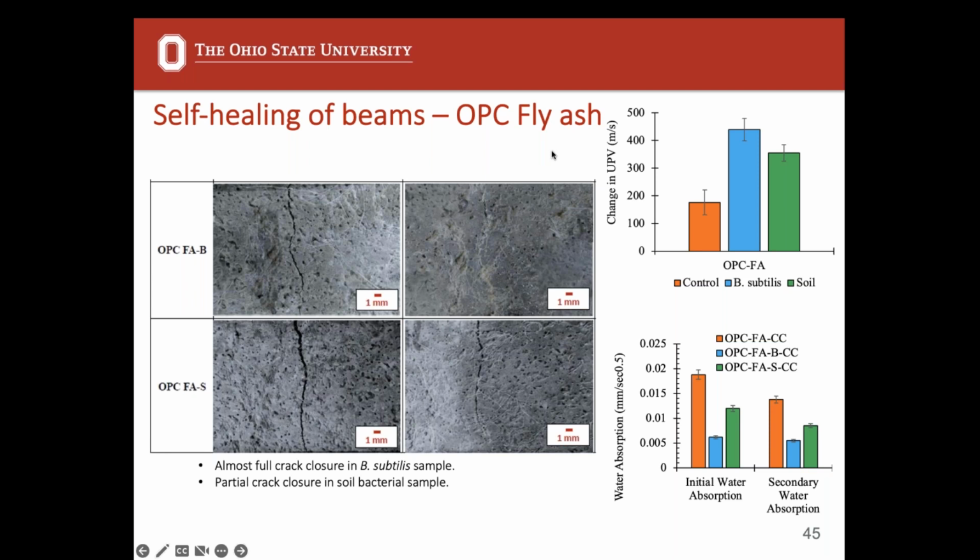How was the crack induced in the sample? So these were fiber reinforced mortar bars. And then we applied a small amount of strain to them to cause the crack in the bottom. We didn't test the bottom flange crack because they were a little bit too wide. It's pretty difficult to hit exactly the crack width that you need. So we tested along the side of the beam, and you can actually see it gets wider at the top here than at the bottom.